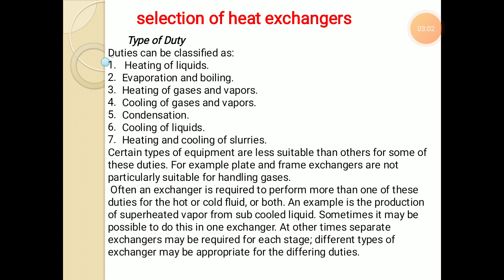Certain types of equipment are less suitable than others for some of these duties. For example, plate and frame heat exchangers, which I had already shown to you, are not particularly suitable for handling gases, but often a heat exchanger is required to perform more than one of these duties.